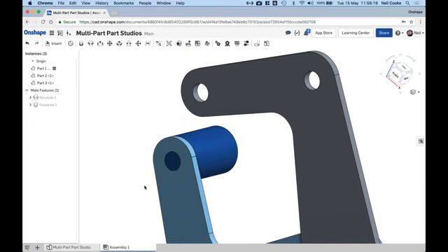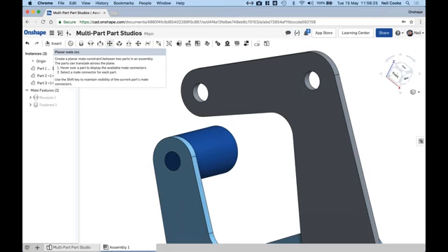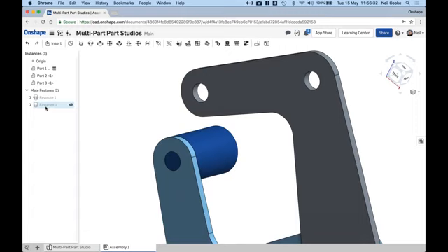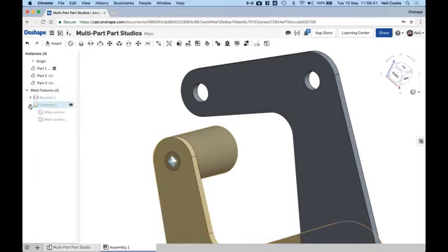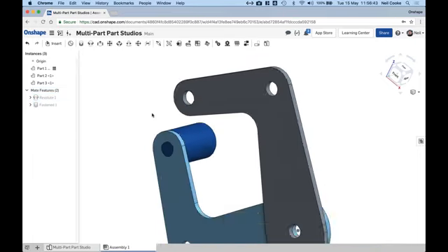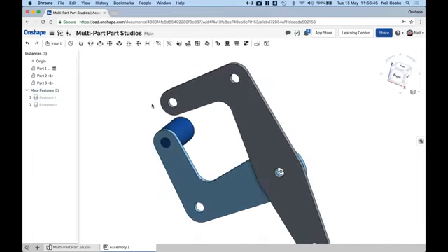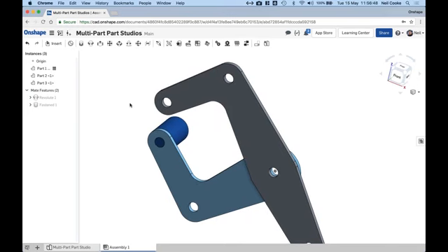So quite often, SolidWorks users will make extensive use of the planar mate to try and get the three mating commands that you would use in SolidWorks, but in reality, most of the time, you can just do it with one. You can also then introduce offsets. You can introduce offsets in there in multiple different directions. You can change angles of things by editing the mate connectors. So there's lots of things you can do in there to generate the assemblies, and most times you can do it much quicker than you can in any other system.